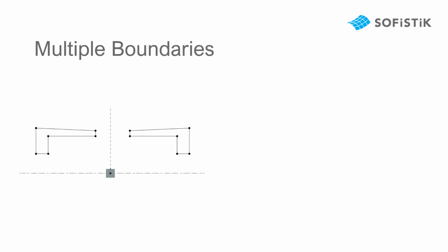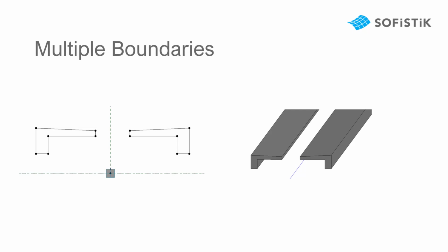Let's talk about special cases. For example, the first thing that I started with was to create multiple boundaries, to create multiple volumetric geometries within a single family to create it along the axis alignment. Using the superstructure command, you would expect the program to simply place the two boundaries along the axis alignment to create this volume, but the superstructure command does not allow you to have multiple boundaries within one family to create the volume, meaning that only one boundary, as you see it here, is viable.